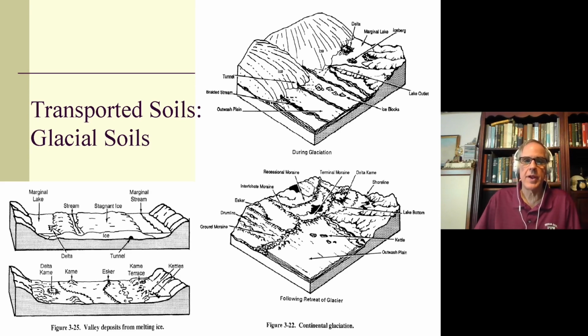But they created probably one of the best known glacial soils, your glacial tills. Your glacial tills are the result of pressure being applied by the glaciers, but when the pressure went away, the compaction and consolidation of the soil meant that the soil was more compact and actually makes an excellent foundation material if it's on the surface. It's not always on the surface, though. Glacial tills are many times below the surface, and we have to basically drive deep foundations to get the benefit of the glaciers.